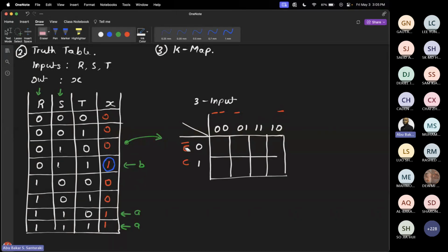So C will also turn to T. I will replace that with RS, and this will be T. So this is RS, RS, RS, RS, and then T, and then T. Now I'm looking for the sequence 0, 1, 1. 0, 1, 1 will occur here. Here I have my RS 0, 1, and my T being 1 is going to be on this row. So that means here I will have a 1.